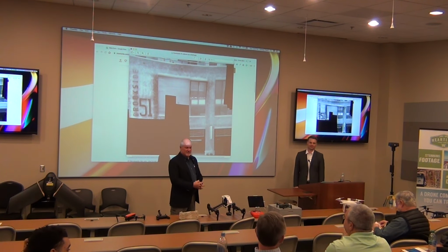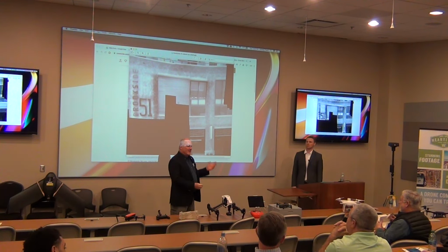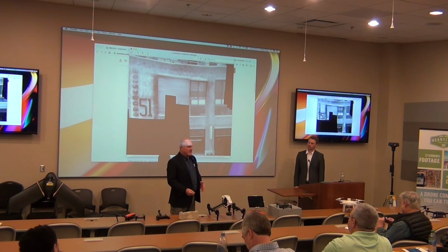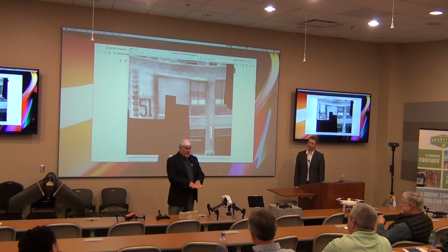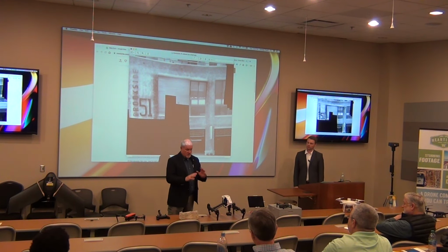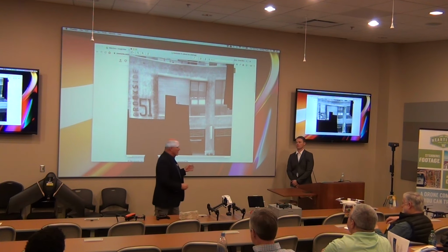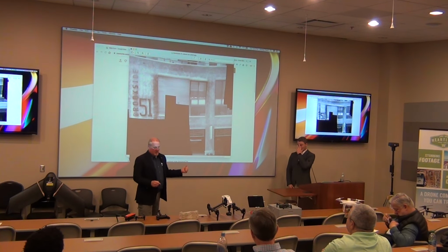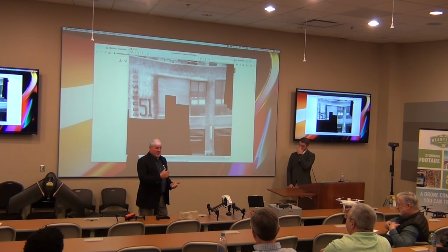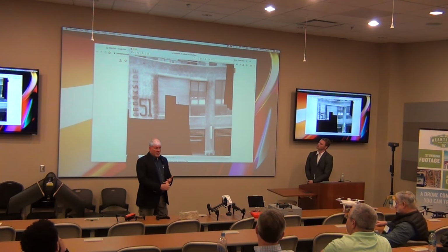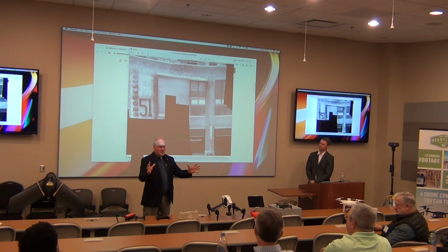No, I'm familiar with thermal a little bit from the roofing industry. Was this flown at night, dusk, morning? Just curious. Yeah, there were 4 separate flights over 3 days, and it kind of flies in the face of conventional thermography, because I'm used to doing flat roofs as well, and knowing that the golden hour is usually the only time when I can do a fully blown roof analysis with thermography. But what we found was, because it was hot summertime, the building was air conditioned, and because the building was fully occupied with either students, apartment dwellers, or a grocery store, we had energy coming through no matter what.